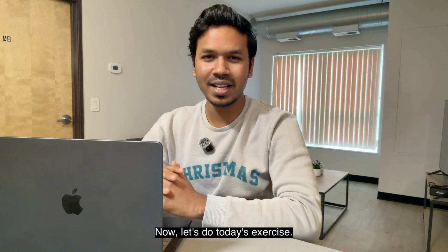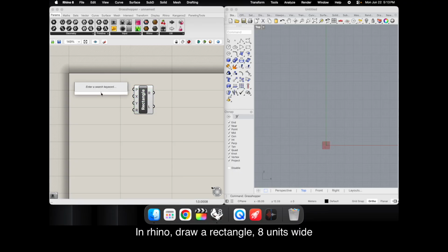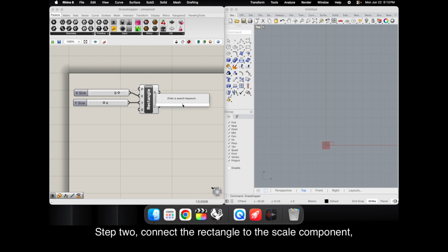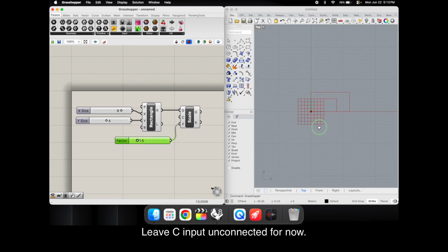Now, let's do today's exercise. This combines all three components. Step 1. In Rhino, draw a rectangle 8 units wide and 4 units tall. Reference it in Grasshopper with a curve parameter. Step 2. Connect the rectangle to the scale component. Set factor to 1.5. Set center to the origin. Leave C input unconnected for now.